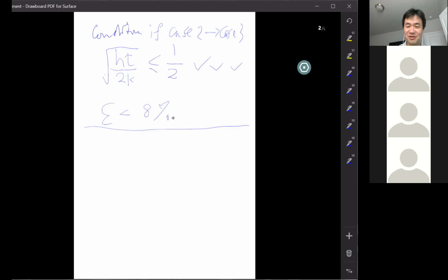In reality, you don't want to see an insulated end. But the reason we have that case is that it has a simple solution, easier to apply. So all of the cases in reality are case two, but 90% of them we can safely say, hey, it's close to case three. Then we apply the case three equation to calculate the thing, okay?